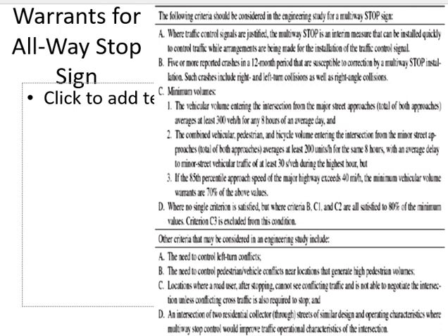Okay, one thing which you already mentioned, that you tried putting a two-way stop sign, but you still don't have enough sight distance. You can consider putting an all-way stop sign as well. All-way meaning all sides will have stop signs. Normally only the minor roads have this stop sign. The following criteria should be considered when you are going to put a multi-way stop sign.